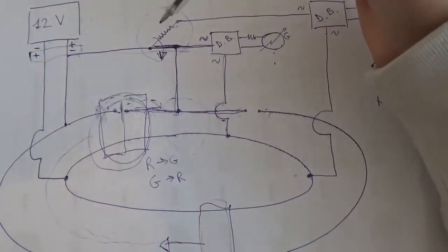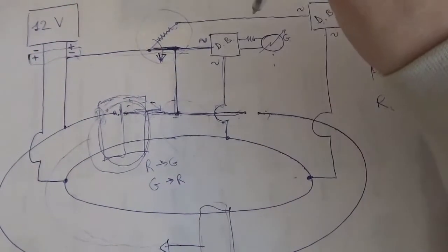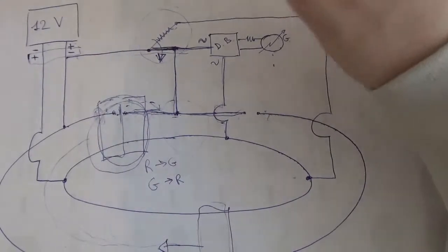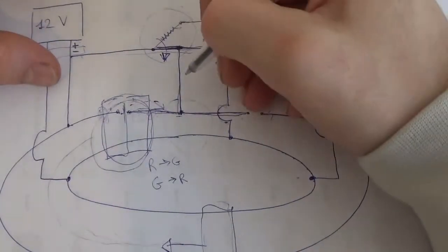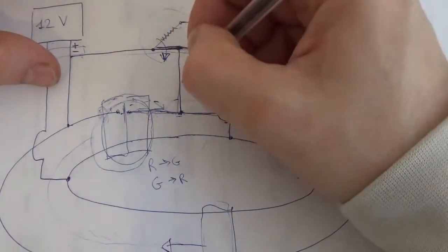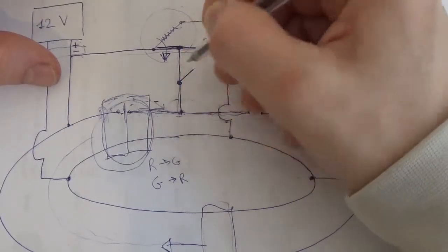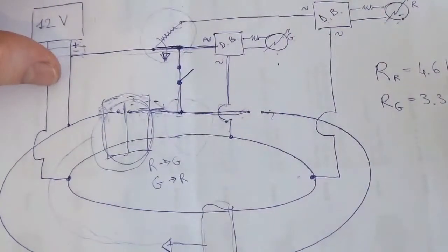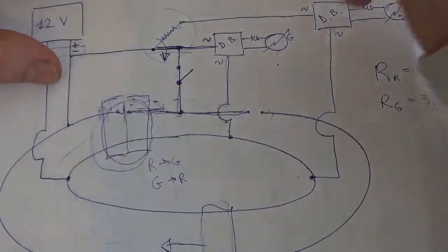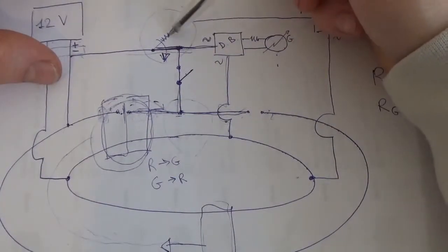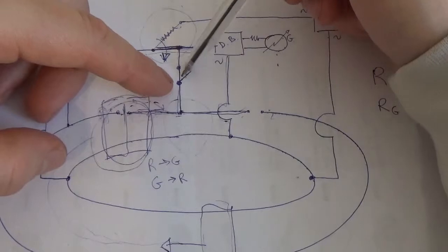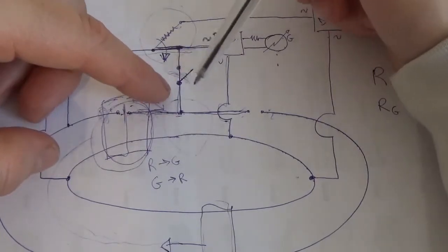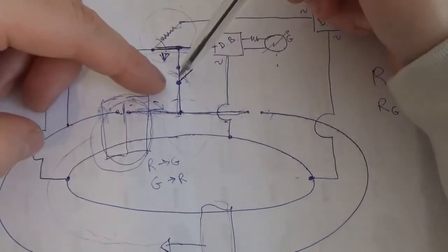I've been thinking about different solutions, some involving transistors, some involving pull up or pull down resistors, but after a few attempts, what turned out to be the only reliable solution was to introduce here a second switch, a secondary one, that working with the right synchronization with this one here was going to allow this circuit to be open at the right time.